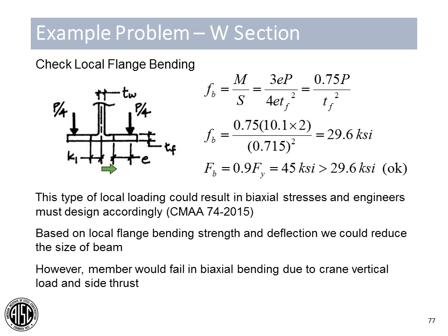If you do for some reason have loading on one side of a flange, or you have some sort of a specialty apparatus, the crane supplier may provide a dimension from a specific point on their trolley to the centroid of the wheel loading area.